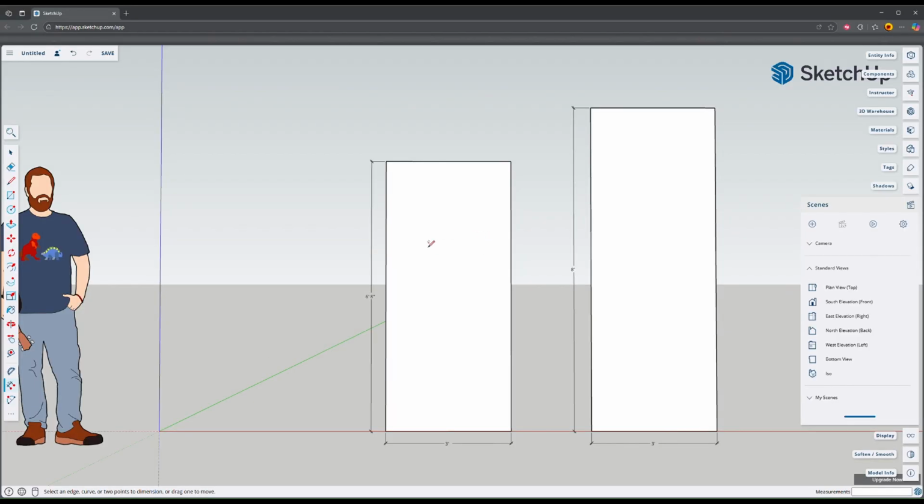Next, select the Offset tool from the tool tray, or simply tap O. Using the Offset tool, I'm going to pull a 1-inch offset to help me remember that the door frame will have a 1-inch lip on both sides and the top. Any design I plan on doing near the edge should be wider than that 1-inch lip, or it won't be seen when the door is closed.